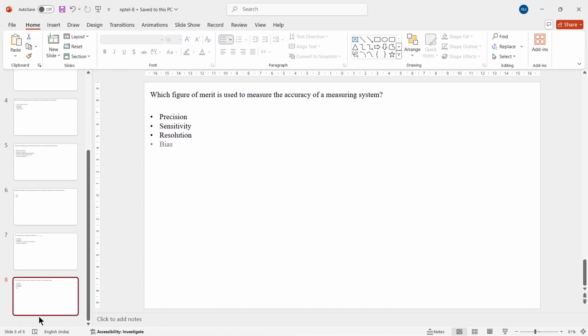You are trying to use these and you make repeated measurements at different points inside the sample, for example points A, B, C, D. If your material is a long cylinder or a long rectangle, you divide it into three portions as A, B, C, D, and then you measure the thickness at these points. Your accuracy, or bias, will be the measure of distance between the average value of these measurements and the true value of the sample itself.